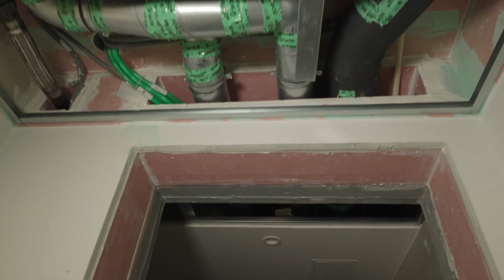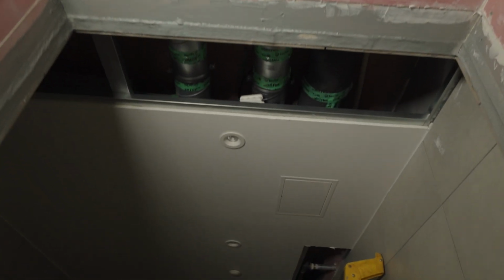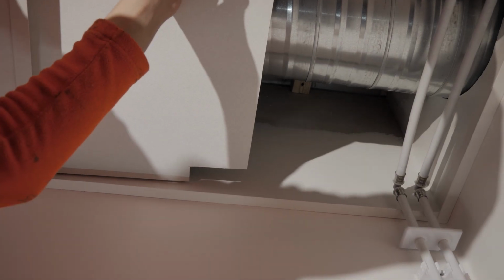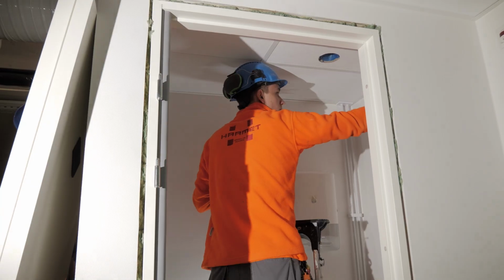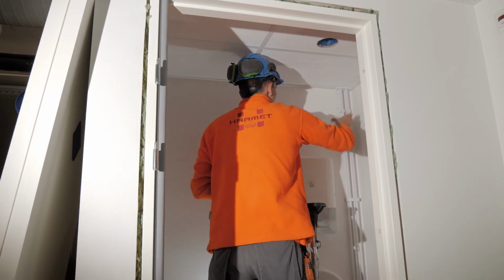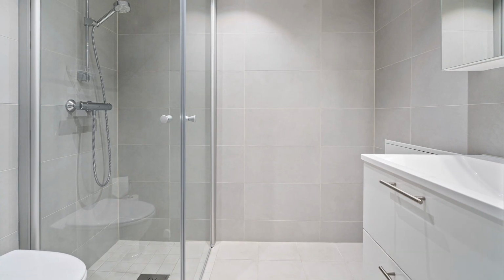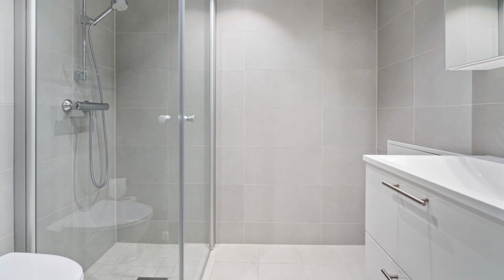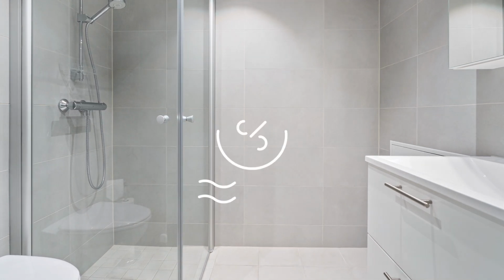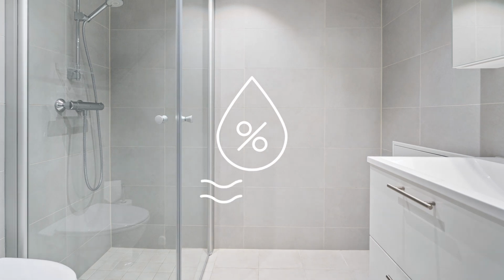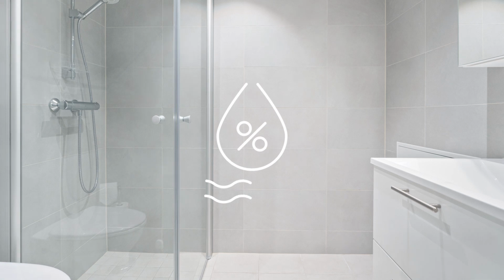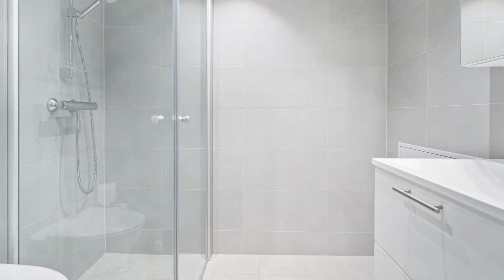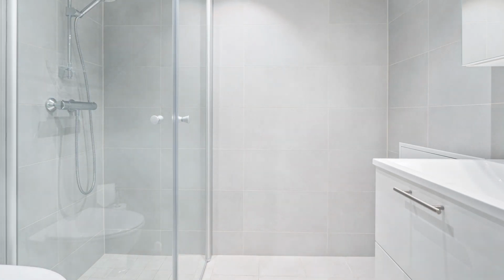Ventilation ducts are installed either in the ceiling structure, in plasterboard boxes in the ceiling corners, or behind suspended ceilings. Suspended ceilings are usually designed either in hallways or in damp rooms. In the bathrooms, the room temperature is generally higher than in other rooms, and relative humidity can easily rise up to 100%, where the air becomes saturated with moisture. Therefore, active ventilation is extremely important.